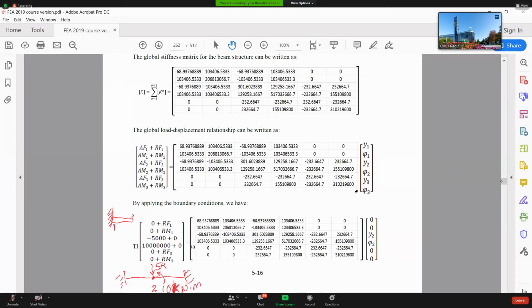That's a 10 kilonewton meter. Then at this node, here's the point, I do not have any reaction. Then reaction moment and reaction force is 0 for node number 2. However, I have 5K and 10 kilonewton meter for applied one. And same goes with the third one.